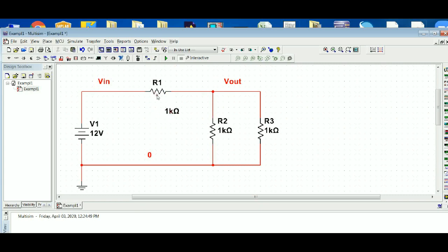Note when I do this, there's a line that connects the resistor to the attribute, the value here, so that if you have a cluster of resistors, by clicking on it and moving it a little bit, you can always see which one this links to. And the same is with the designation of the resistor too. So this came out of the library as R1. And if I wanted to change it to something else, I could certainly do that by double clicking it.